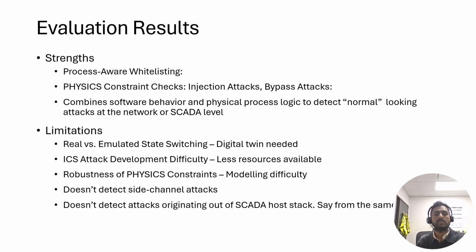Advantages are that by using the physics constraints, it is able to whitelist what it calls SCADA API actions or SCADA commands that are considered normal for a specific state of the process. By combining software behavior and physical process logic, they're able to detect attacks that might look normal to a firewall.